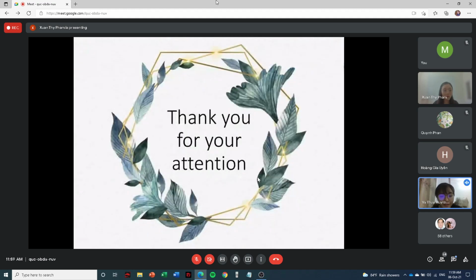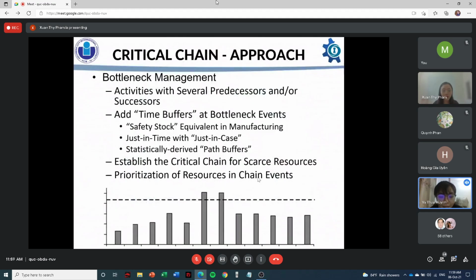So next is the 5 steps of the theory of constraints. The aim is to keep the constraint or the bottleneck as efficient as possible, because only the efficiency of the bottleneck is a critical factor to the overall performance. There are 5 important steps to improve performance of a chain. Each step will be explained with an example in production terms.